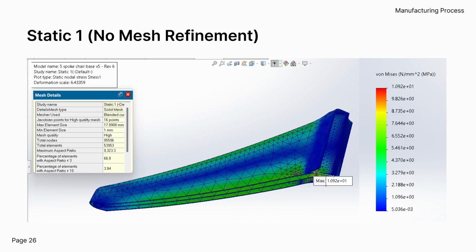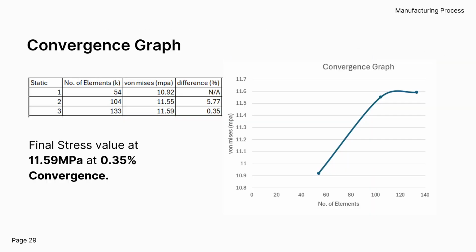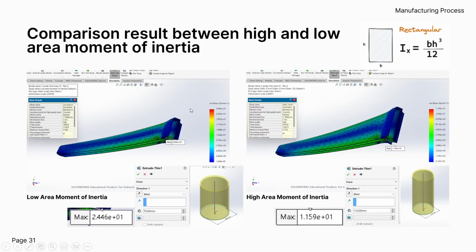Going through roughly FEA analysis, how to do FEA analysis, a deep dive using mesh refinement, local mesh refinement. Understanding things like elements, understanding pressure, where to put your pressure. And then plot all of them into a convergence graph with less than 2%, and to be able to hit your targeted stress level, basically.